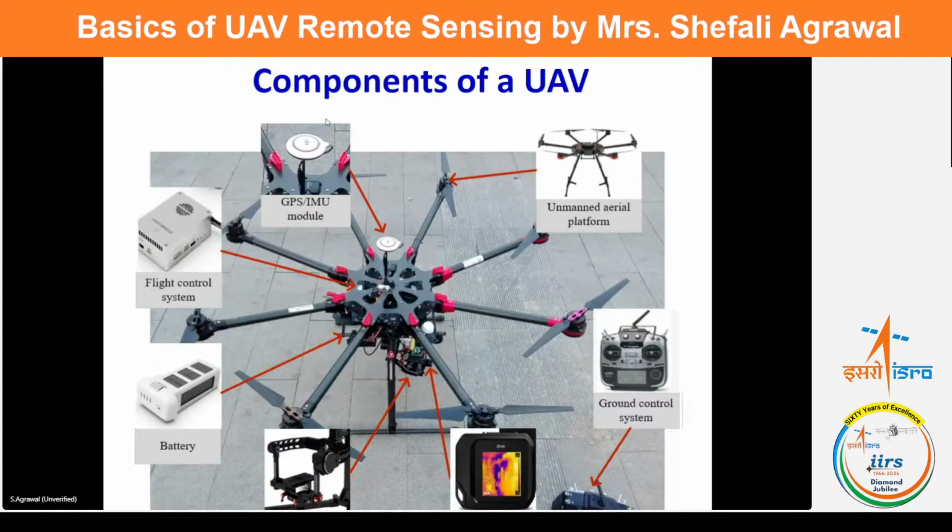Between the power source and the motors, there is an electronic speed controller. This device regulates how fast each motor spins, and it acts like a messenger. It ensures that the motor spins at the exact speed required to keep the drone in balance, based on the commands it receives from the flight controller, right?